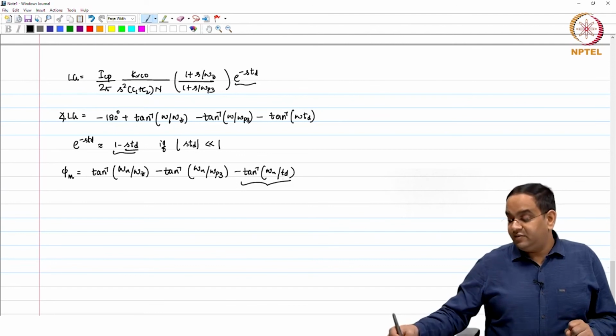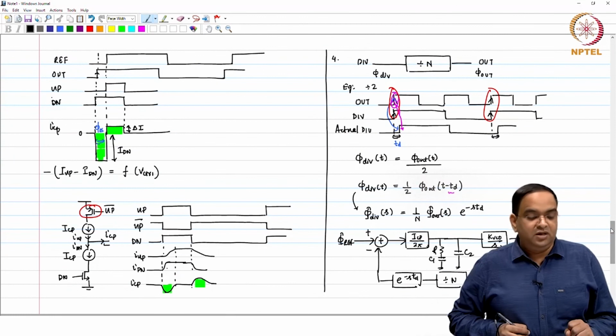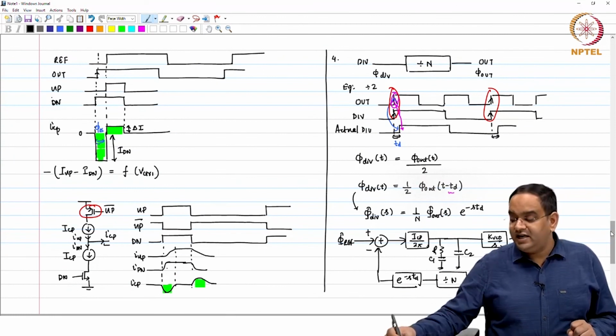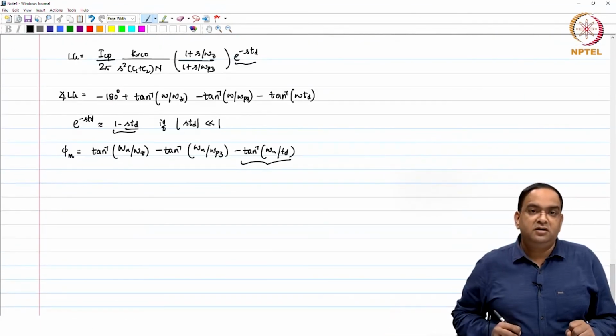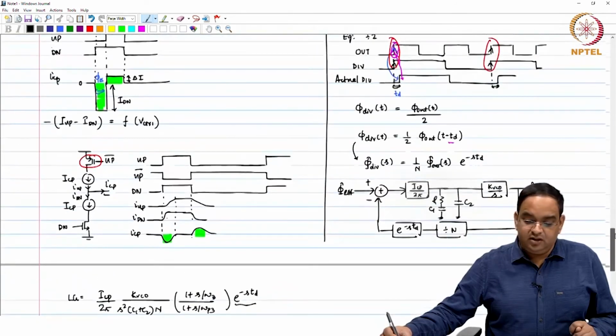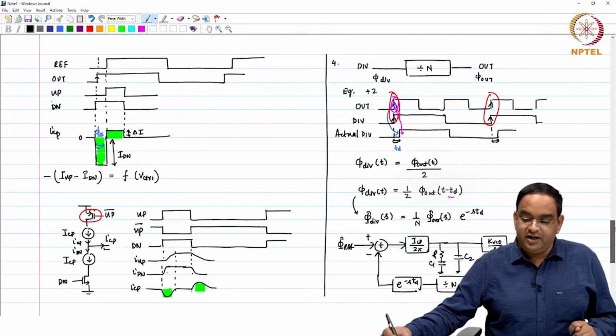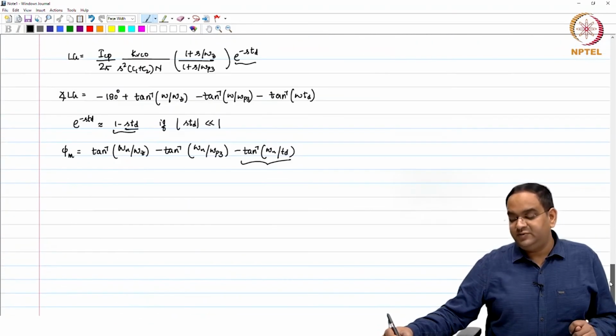Okay. If for some reason you introduce any other delay in the PLL loop, just be aware of the consequence: any delay is going to add a right half plane 0, and it will reduce the phase margin. Okay. So, this concludes a few of the main non-linearities which we experience in charge pumps. Okay. Thank you.